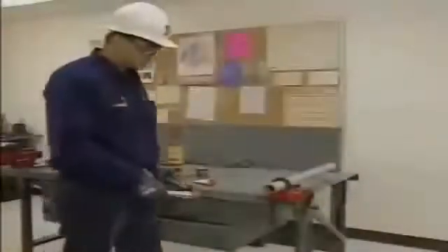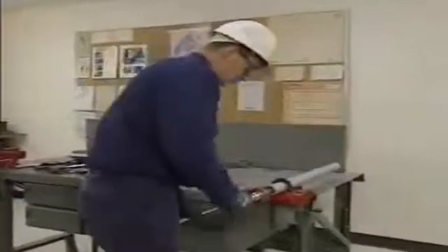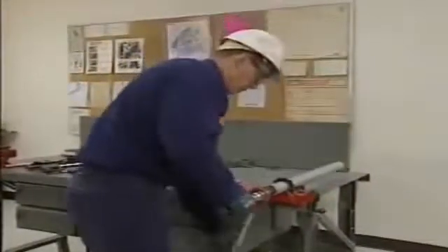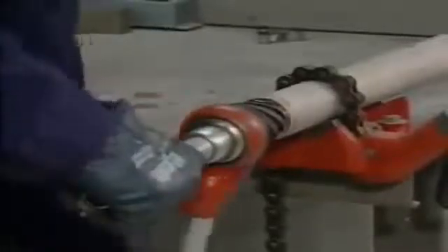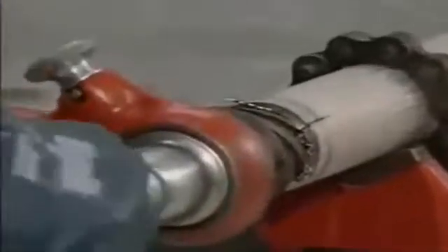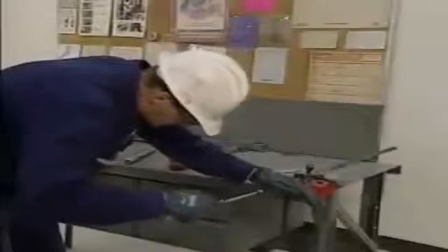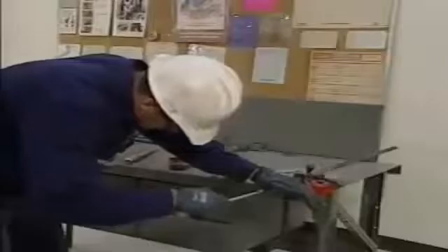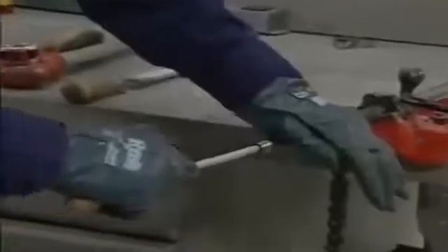Insert the reamer or file into the pipe enough to exert a slight pressure without damaging the pipe wall, and rotate the reamer or file inside the pipe until the pipe surface is smooth and free from burrs and ridges. A rat-tail file should be used as a last resort, when a reamer or a half-round file will not fit inside the pipe. Rat-tail files can leave marks on the inside wall of the pipe, which makes the pipe wall thin and susceptible to early failure.